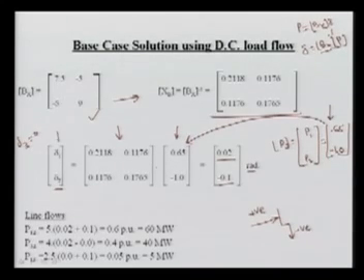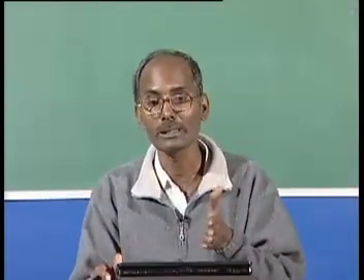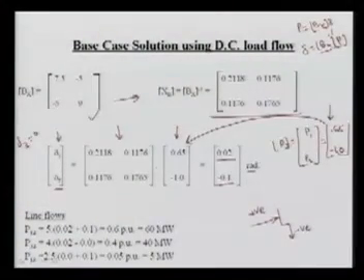So these angles we always get in radian, not in degree. Normally people get confused in the conversion of per unit quantities. If you are taking actual values for P, then everything is wrong. This matrix is on the per unit impedances of the lines, so the result is in radian.